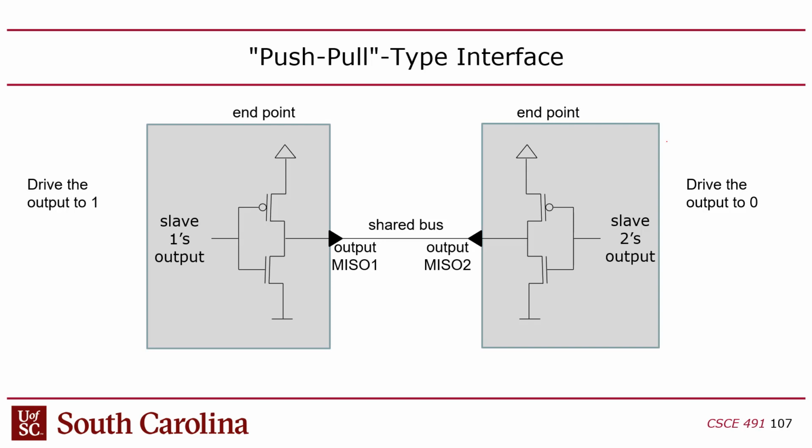That output bit goes to both of these transistors, and because the transistors are activated on different logic levels but getting the same input, they are only going to be able to pull their output to high or low, never both at the same time, right? So that's important. That's why CMOS logic is what all modern chips are made from.